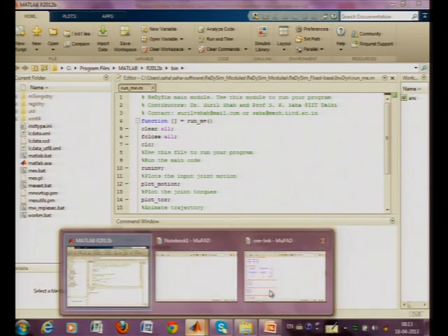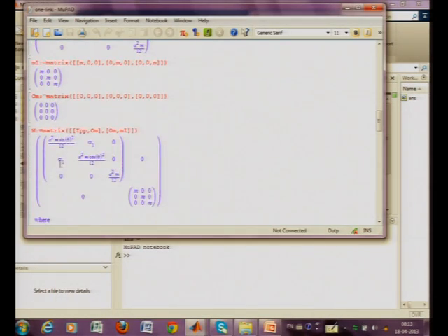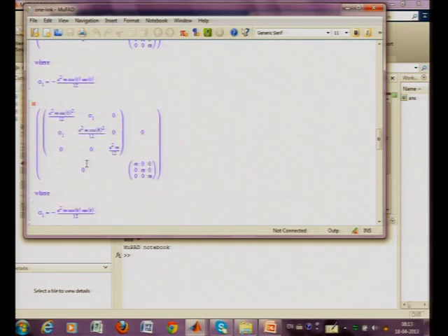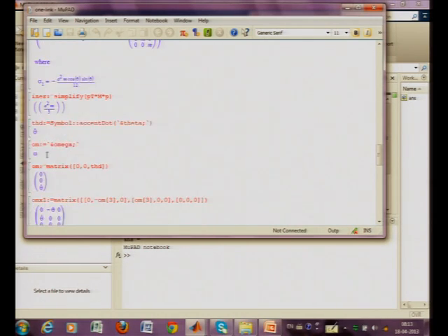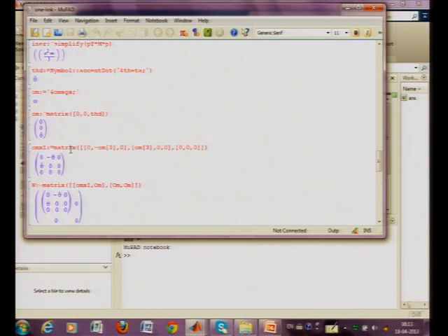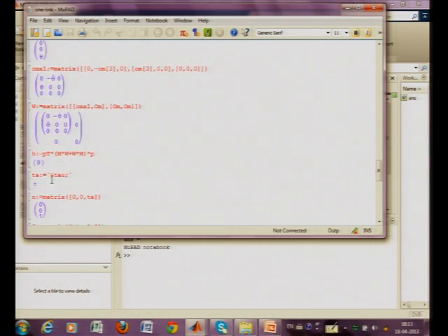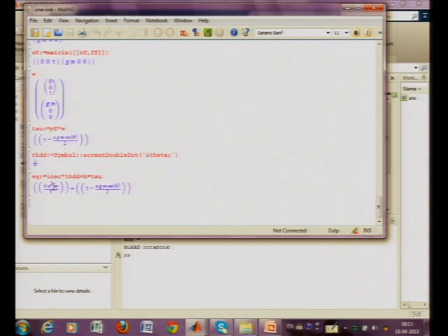Then I form the mass matrix, and do the operation P transpose M P, which gives you m a square by 3. Then I compute the component of H, the vector of the multiplicative theta dot square terms. For this simple case it turns out to be 0. So the result is 0 here, and then the final expression is here.